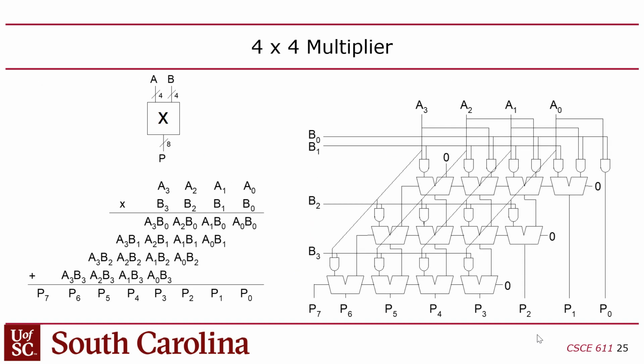Okay, and then we talked about multipliers and dividers. Now, the idea with the multiplier design we talked about is you're basically just using these AND gates to turn off, to basically zero out one of these things that you're adding, right? One of these rows you're adding, depending on the multiplier. So if any of the bits of the multiplier are 0, for each one of those bits, you need to zero out the corresponding row down here, right? And that's basically what's happening here.